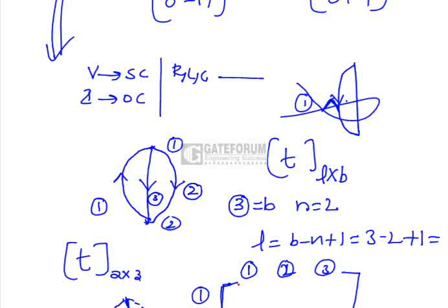After marking these, now if you see here, the loop matrix is drawn in terms of voltage drop in a loop. Now consider the direction of current like this. This is the direction of current. We have to consider it in terms of loop direction always. Similarly here the direction of loop current is like this. Now this is loop 1 and this one is loop 2. Now mark the values of this loop matrix.